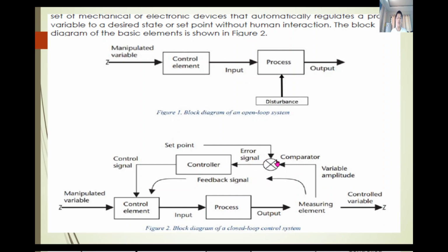There is an error signal. So compared to the set point of 80, let's say already 95 here. So there should be an alarm on that measured value. So that is already alarm.